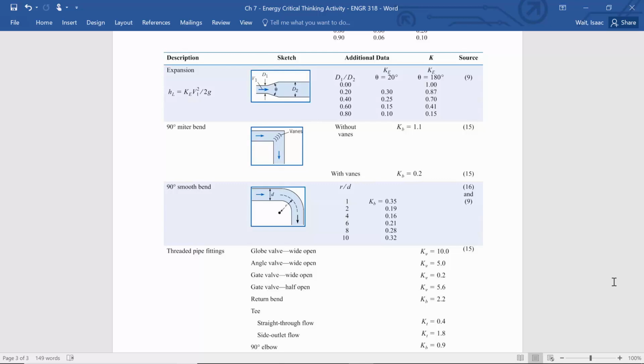It's still changing from x to y, so you end up with the same endpoint, but we're not inducing turbulence as rapidly. The energy loss because of an abrupt change in direction is going to disturb the flow patterns. It's going to introduce more random movement inside of the pipe. And so there are energy losses because of that disturbance.